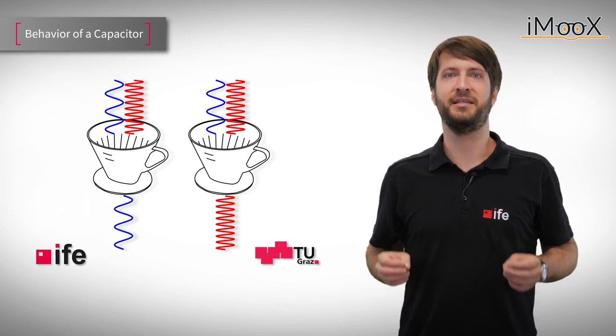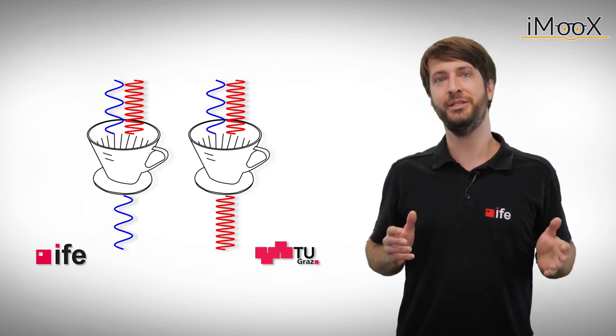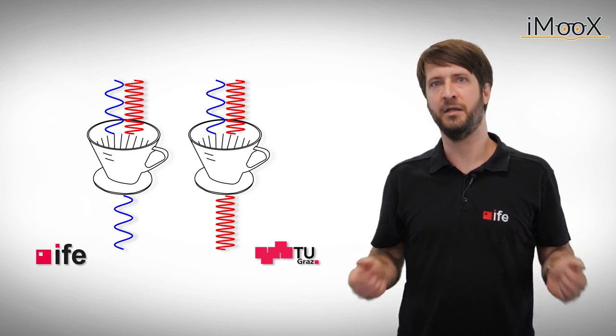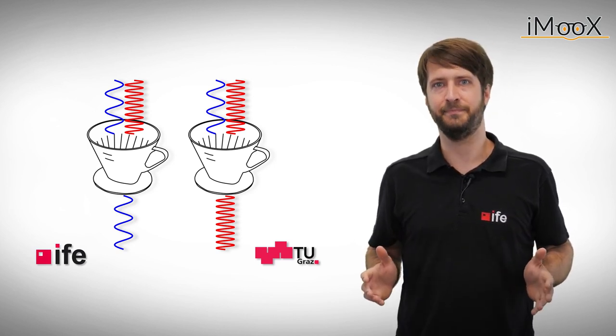We now know that at the frequency extremes, our filter will behave just the way we want it to. But what happens in between those extremes, and where is our corner frequency Fc? To get to the bottom of this, we again need to think of our filter as a frequency-dependent voltage divider.